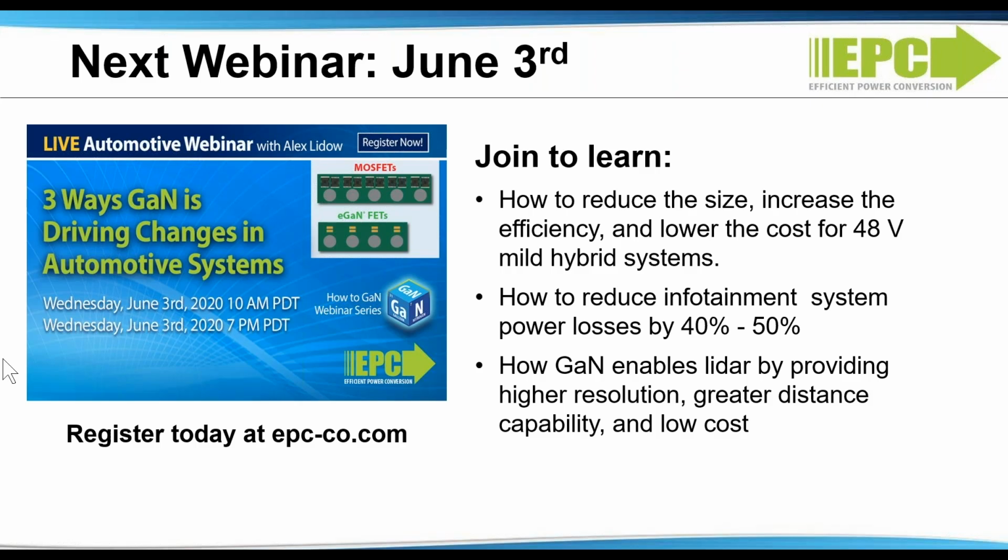I don't know if you can see your chat window, Alex, but what are the isolation requirements for on-server board converters? In previous architectures where the 12 to 1 volt converter was on board, there was no isolation. Would there be a need now, since there is more power electronics on board, which may increase leakage current, grounding issues, etc., requiring isolation between 48 volts and 6 volts?